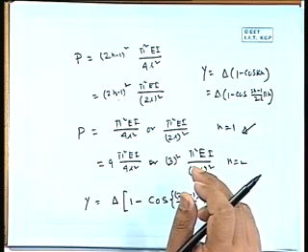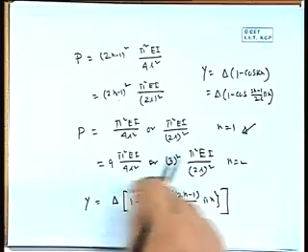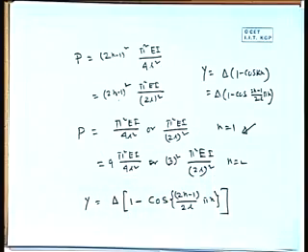So earlier we got how much? Pi square EI by L square. So pi square EI by L square is a very standard form. With that, if you just divide by 4, so here also if you change the mode, there is a factor multiplied. Pi square EI by L square is a very unique case, where we are talking about a column with both ends hinged.